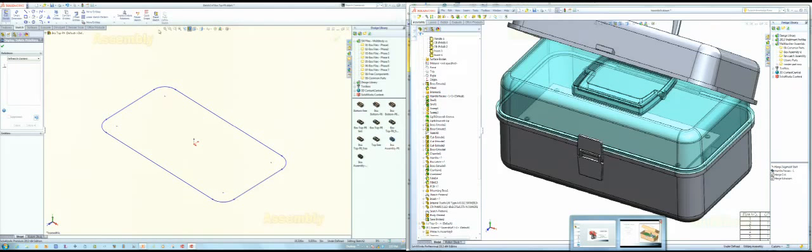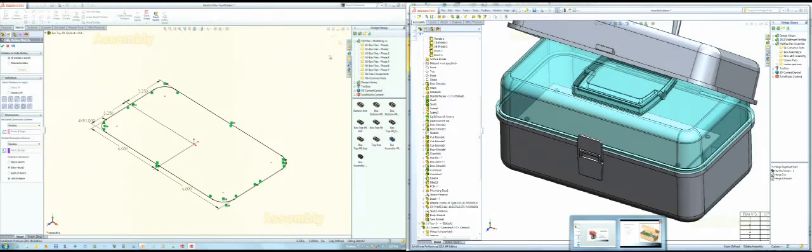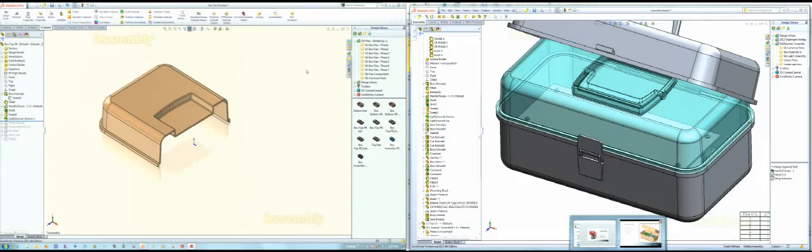Well, that's where that other tool that's in here comes in handy. Let's get rid of this. Fully defined sketch. Tell it to calculate, say, yeah, that looks pretty good right there. Now fully defined, get out of the sketch, and I no longer have a reference there. Fully defined sketch, great tool.